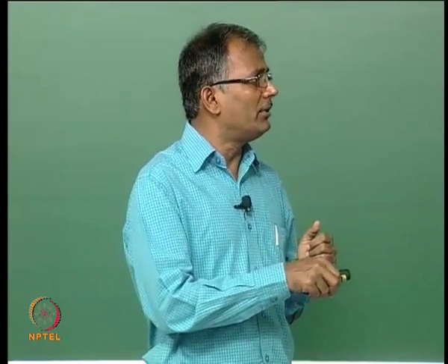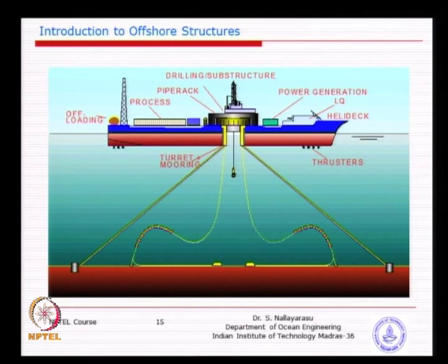The second difficulty is designing a bearing system by which the whole ship can rotate. It is not such a small bearing like what you see in motors. The diameter of that bearing could potentially be 20-25 meters. So, you could see a large diameter bearing by which it could revolve around. This has become very common in the FPSO, because you do not have a mooring line problem, because mooring lines are not taking any load here.